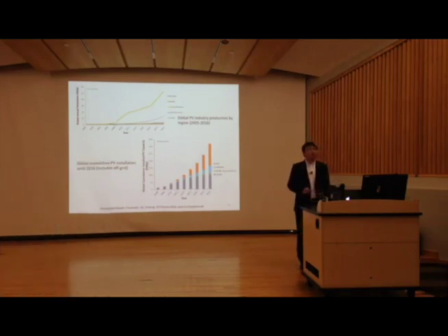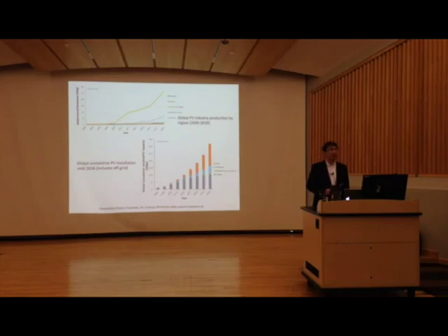In my understanding, the reason that silicon, both polycrystalline and monocrystalline, has dominated the marketplace for many years is that not only does it have reasonable efficiency, but it is also incredibly durable, looking at 40 and 50 year lifetimes. And also its degradation rate is fairly low, less than 0.5% per year. So these third generation technologies that are coming along, how do they look in terms of durability and degradation rate?